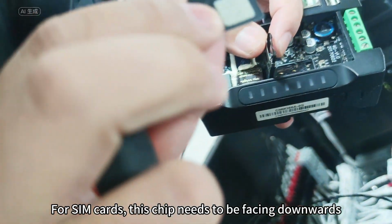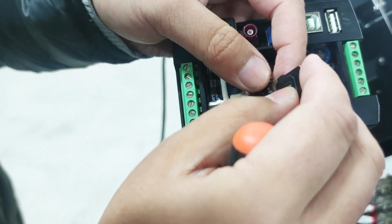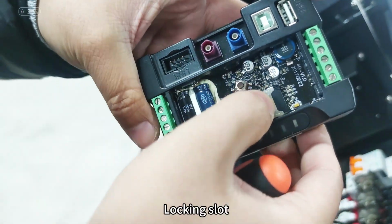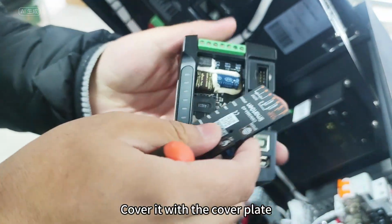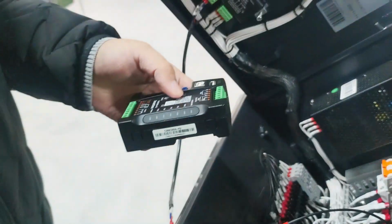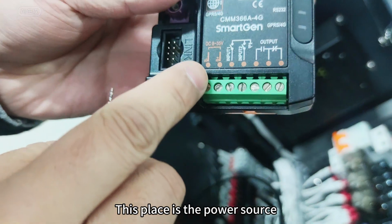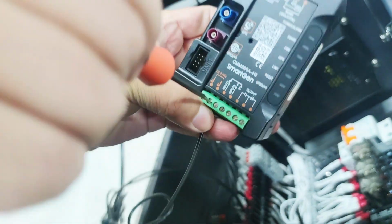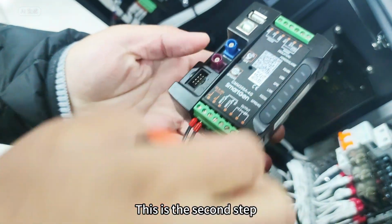For SIM cards, this chip needs to be facing downwards. There is a gap here. After installing it like this, push up, locking the slot. Cover it with the cover plate. This is the first step. Next, let's connect the power cord of this cloud modem. This place is the power source, DC8-35V. This is the second step.